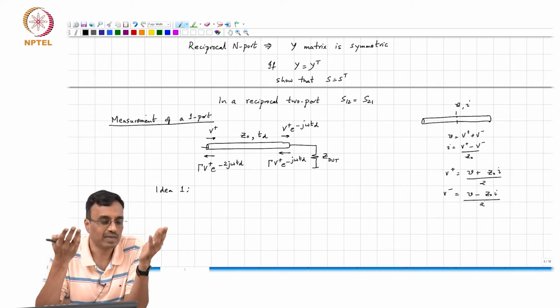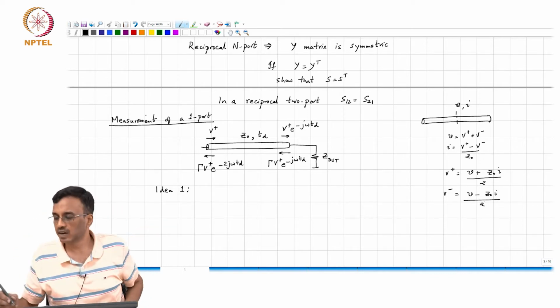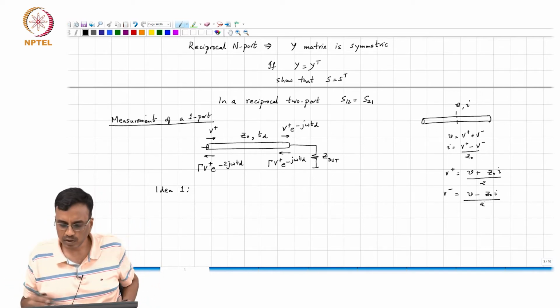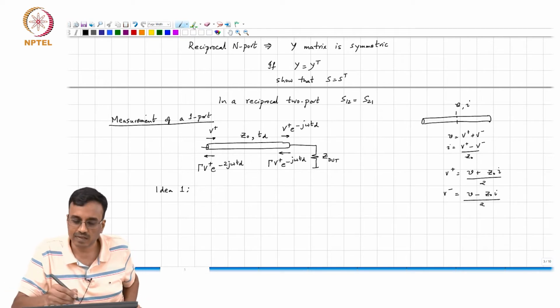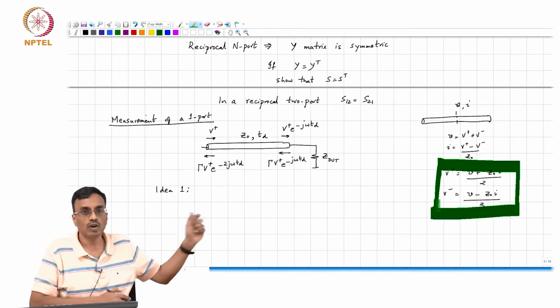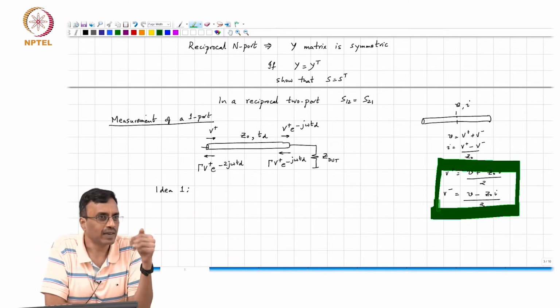Yeah. So basically you couple an inductor somewhere, so that you use mutual induction, right. In reality it turns out, I am not sure I will have time to discuss it in this course, but it is possible, and the principle is this: if you want to find the forward and the backward going waves, you have to compute voltage plus Z times current and voltage minus Z times current. The only question is how you accomplish this.